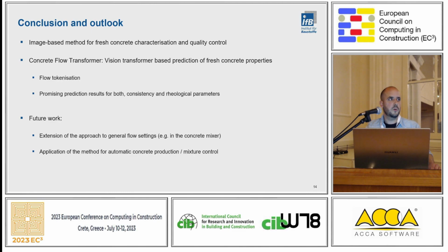In future work, we aim at not only applying this method at the delivery, but also during production in the concrete plant, where we plan to install cameras in the concrete mixer already to determine the fresh concrete properties there, in order to obtain the capability to adjust the mixture in real time during production.